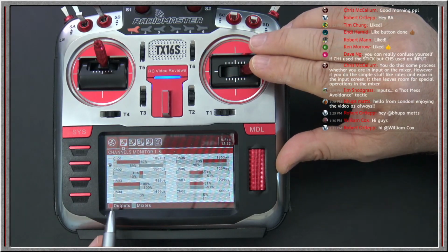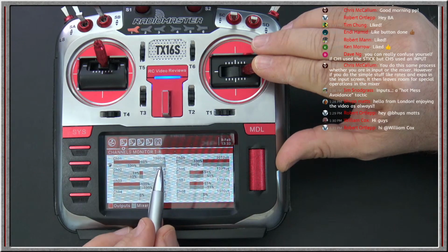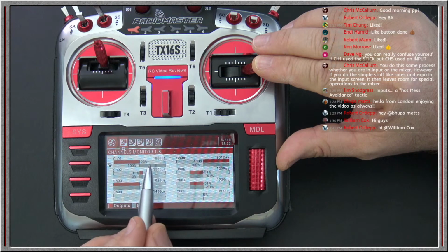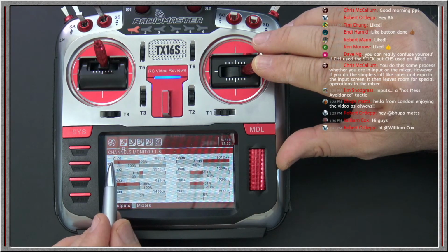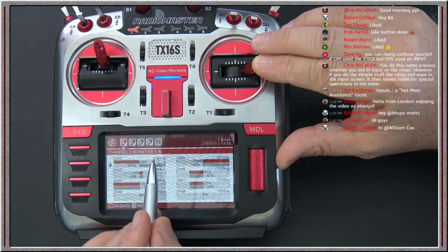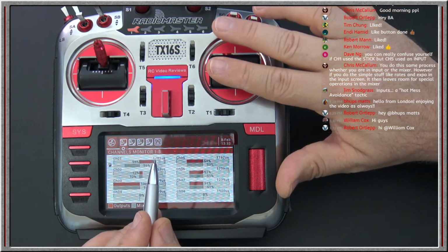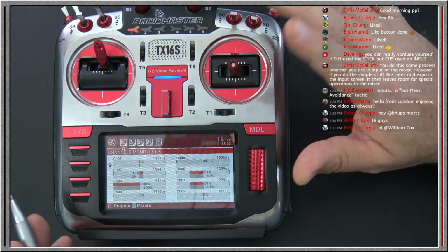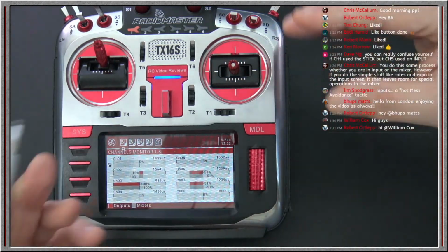The second thing is that the mixer still goes to the right. You see how the mixer is still going to the right, and the mixer is going to the right on channel 5, but now the output's going to the left. That's a channel that's been reversed. Now look at our outputs though, they still apply. I still have 1000 as an output, and I've got 2000 as an output going this way. So there's the nature of flipping a servo.